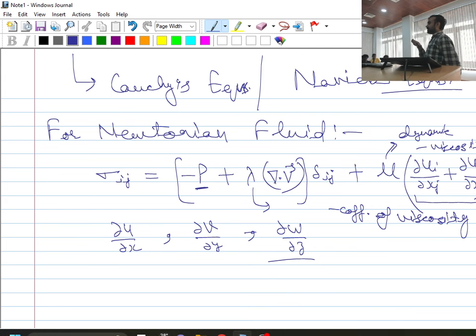In the previous lecture we have seen it is nothing but the continuity equation or conservation of mass equation for steady incompressible flow, but I have also told you this is equal to volumetric dilatation. But what is this other term? If you recall, this is the term which represents the deformation of the fluid element. Deformation of the fluid element will give us shear stress. Point is clear?